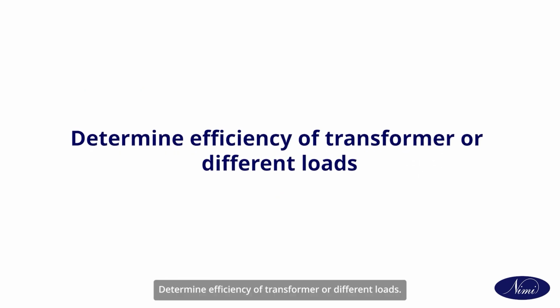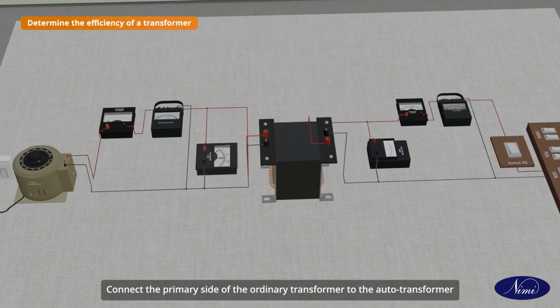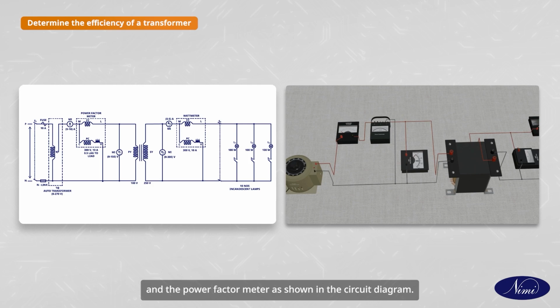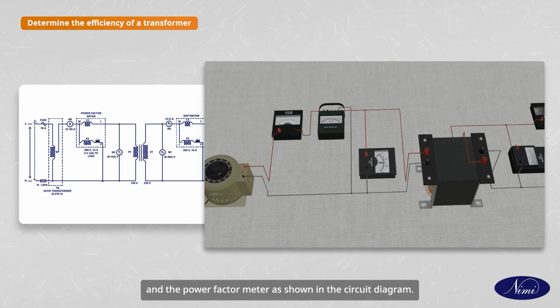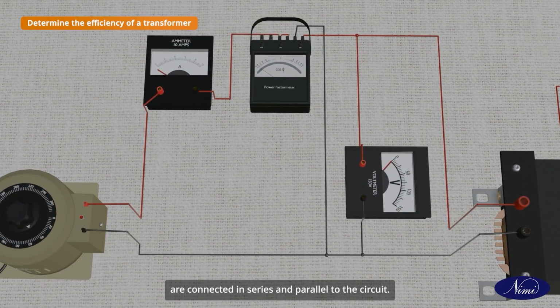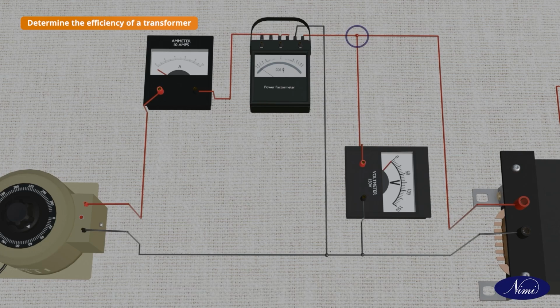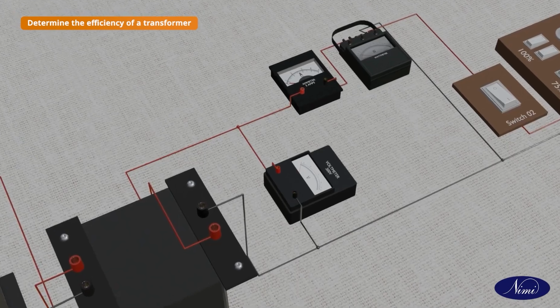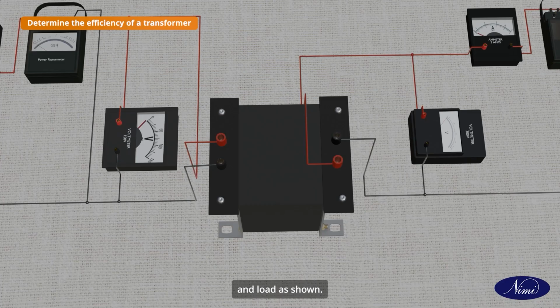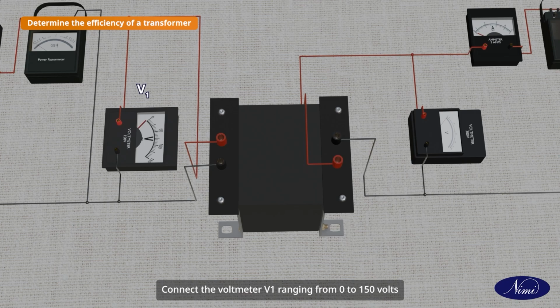Determine efficiency of transformer at different loads. Connect the primary side of the ordinary transformer to the auto transformer through ammeter A1 in series and the power factor meter as shown in the circuit diagram. Ensure the current and voltage coils of the power factor meter are connected in series and parallel to the circuit. Connect the ammeter A2 and wattmeter between the secondary winding and load as shown. Connect the voltmeter V1 ranging from 0 to 150 volts parallel to the primary winding and voltmeter V2 ranging from 0 to 300 volts parallel to the secondary winding.